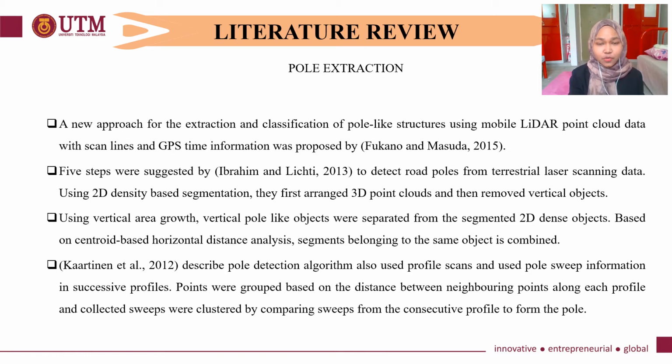So based on findings, 5 steps were suggested by Ibrahim and Lichti to detect road poles from terrestrial laser scanning data, and then using 2D based segmentation, they first arrange 3D point clouds and then remove vertical objects. Then using area growth, vertical pole-like objects were separated from the segmented 2D object based on centered based horizontal distance analysis.